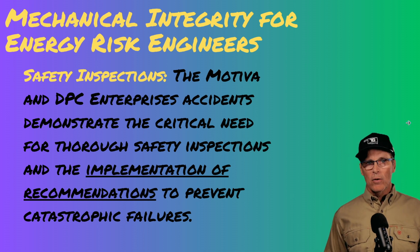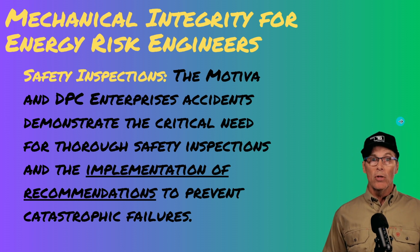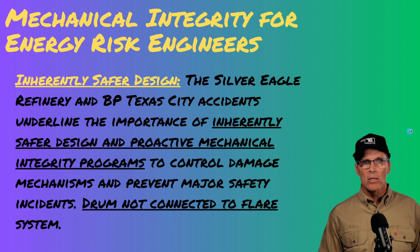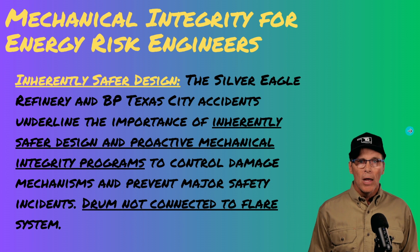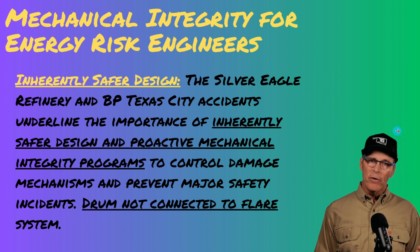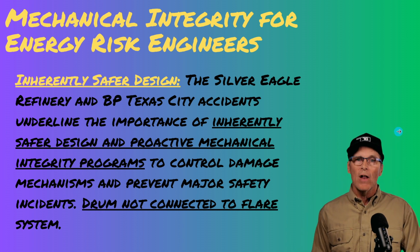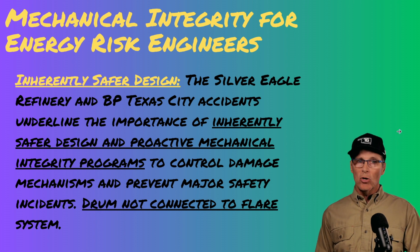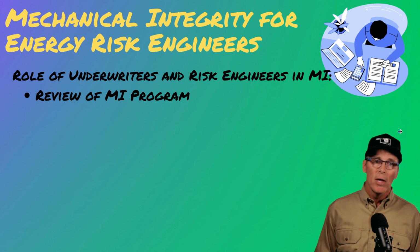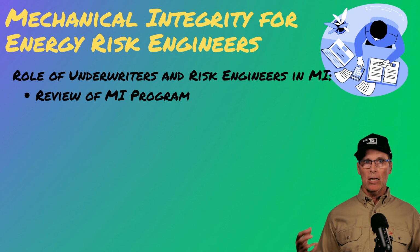Here it is again. They're inspecting, they have a corrective action recommendation, but they didn't implement it, so they fell victim to it, which is the worst kind of incident to have, one that you could have prevented. An inherently safer design. At the Silver Eagle and BP Texas refinery accidents, the drum relief line was not connected to the flare system, so it just blew hydrocarbons out that eventually caught fire and exploded.